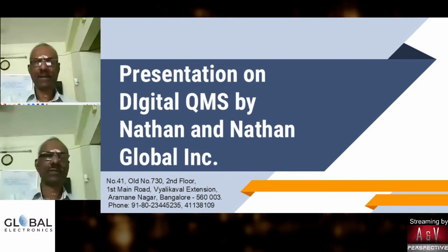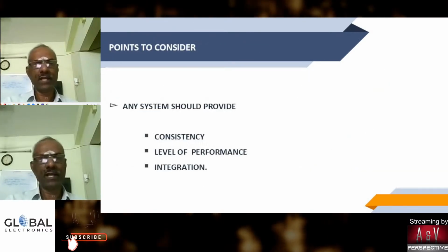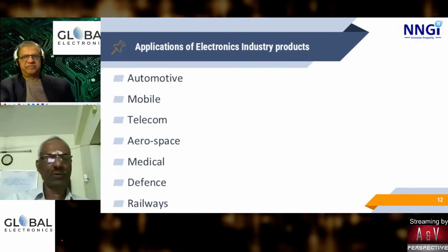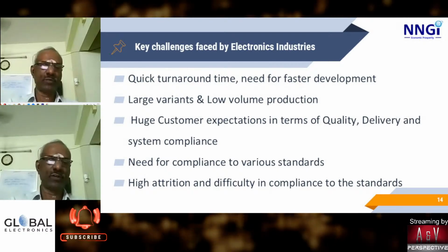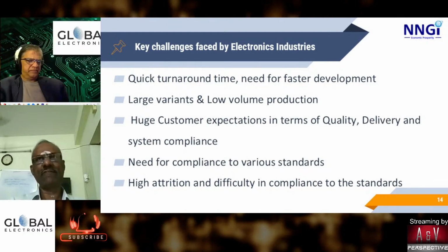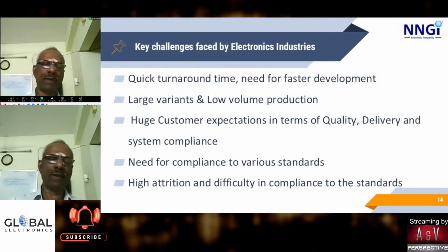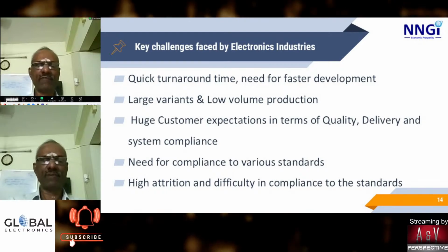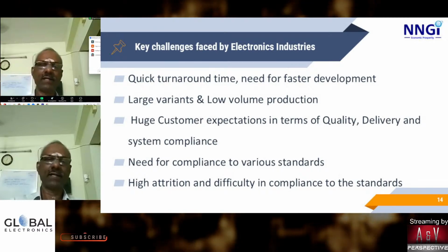Yeah. Sure. So I will just explain the process flow, how the quality modules are getting integrated. It starts with a new product development cycle. Then it assesses the risk management related to the new products. Then it goes through the APQP cycle, where the entire 5 phases of APQP are driven. Then it goes through the PPAP route. In the APQP route, the process flow diagram, FMEA, control plan, SPC, MSA, and SPC are integrated.